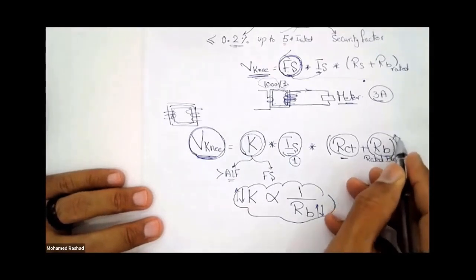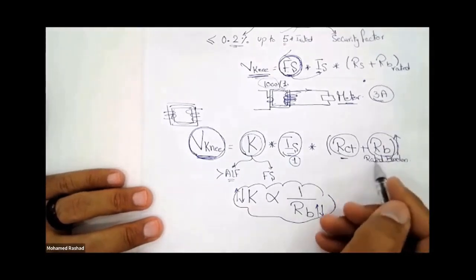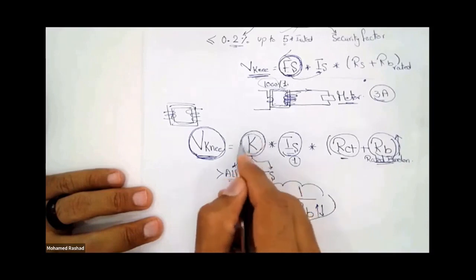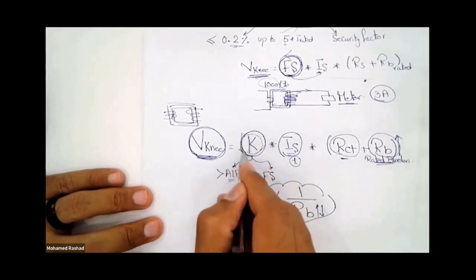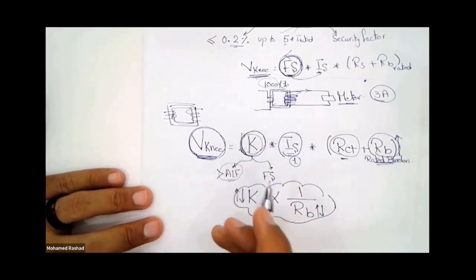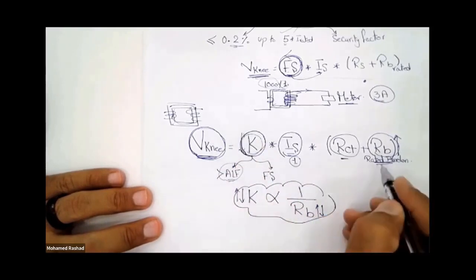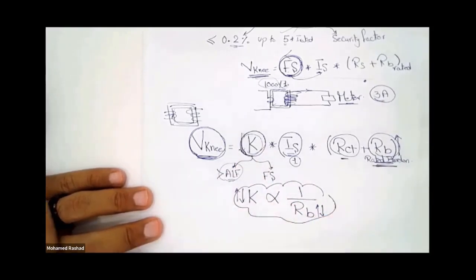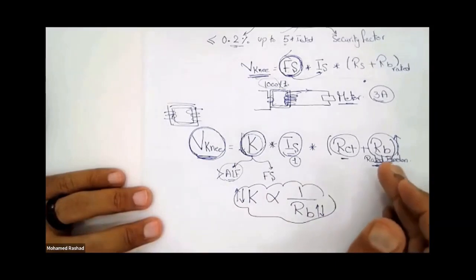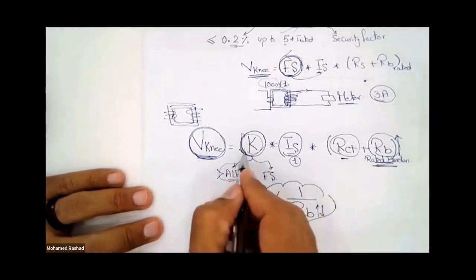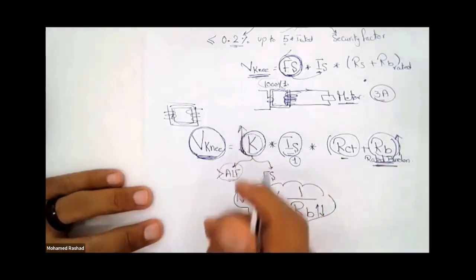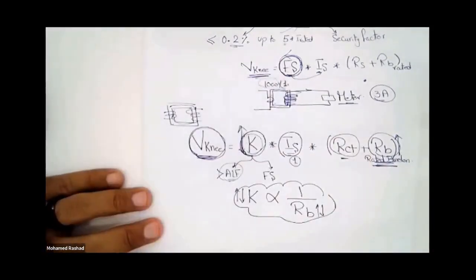If I increase this burden beyond the rated burden, I might find that I reach saturation at fewer multiples of the accuracy factor. Consequently, I will have a problem. That's why I need to ensure that I reach the rated burden or less than the rated burden. So I maintain high saturation at a high number of multiples of the current, which is very good.